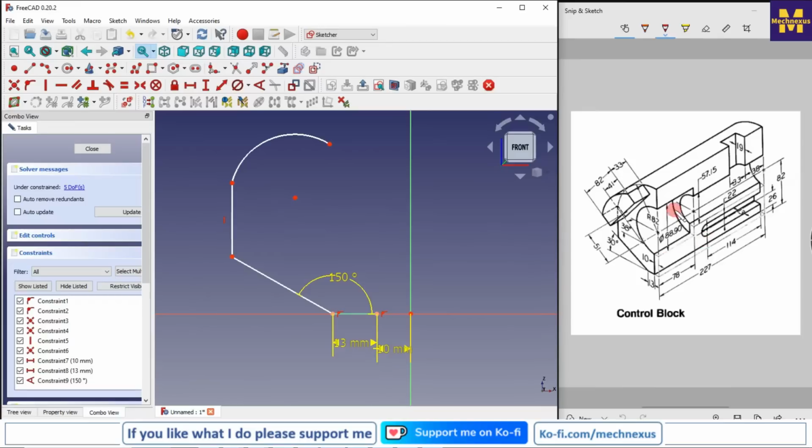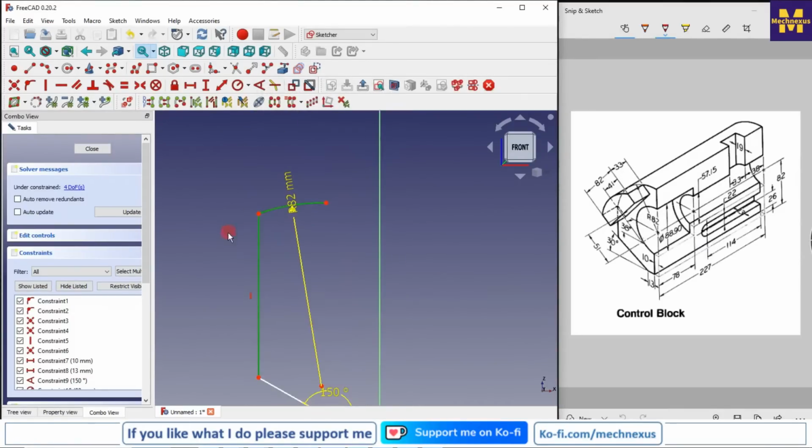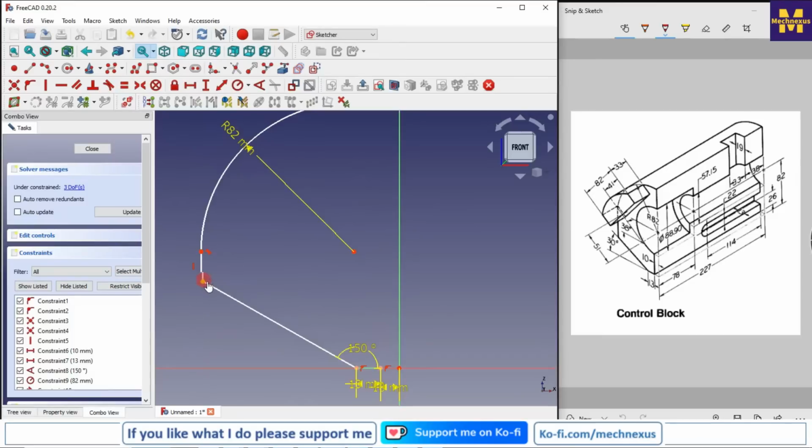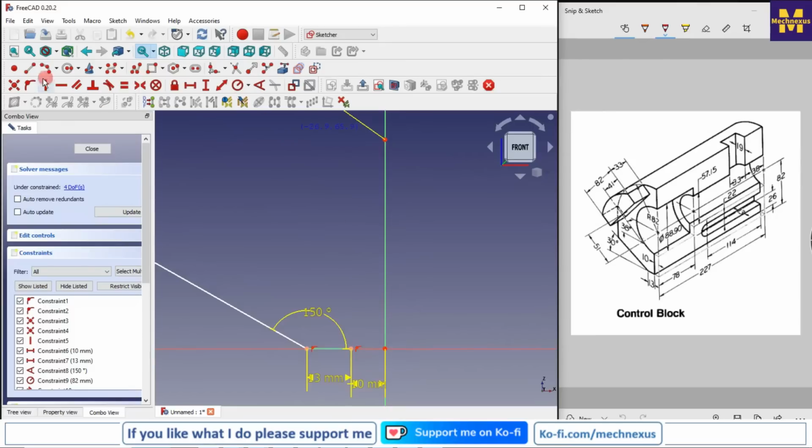and now we will see the outer one, meaning this arc. The outer one is R82, which we can see here. So I will select this and give radius 82, and I will make it tangent, and now we will draw a line, and on the bottom side I will also draw a line,